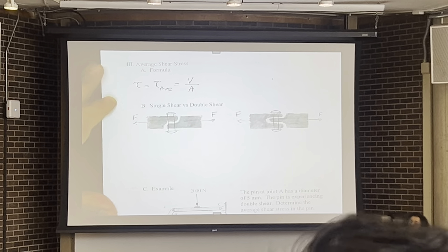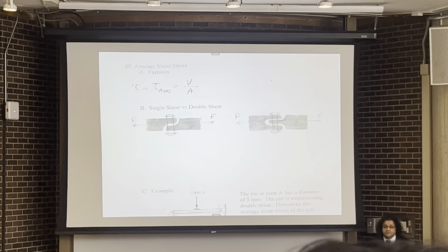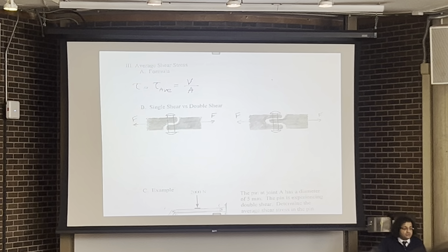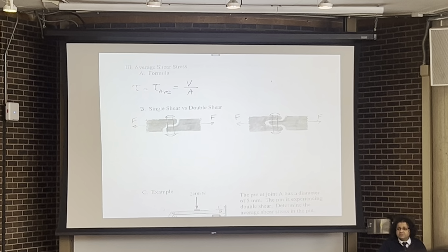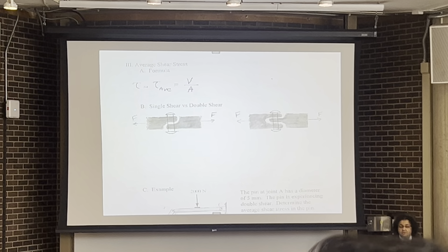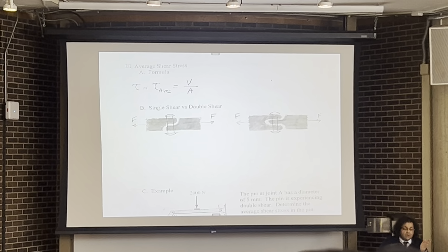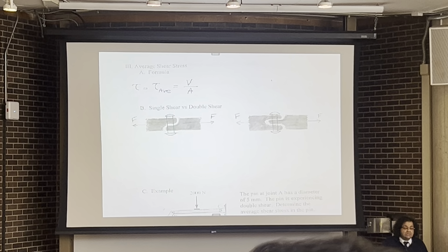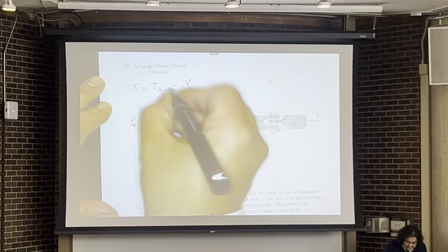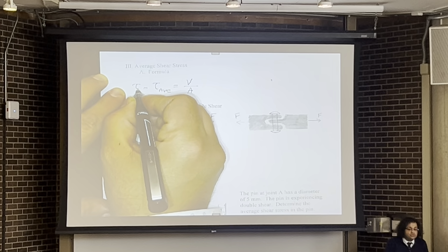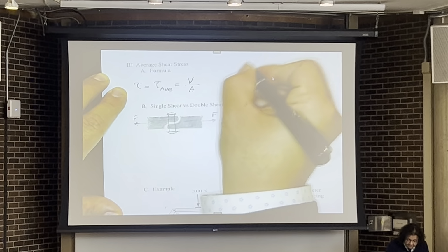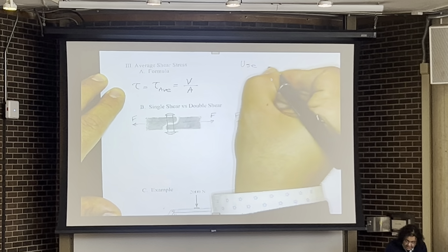But where can we use this equation? Engineering experience has shown that it's fine to use this equation, for example, for pins and bolts. And in structural design, we always do that. We always use this assumption that in order to calculate the shear stress, we can just divide the shear force by the area. So we can definitely use this on bolts.